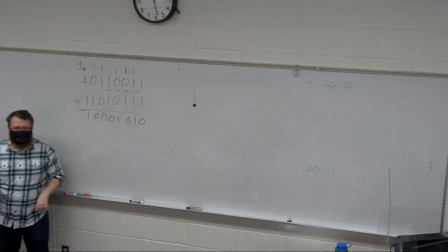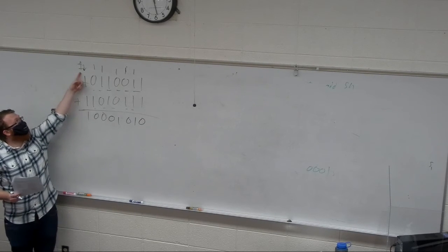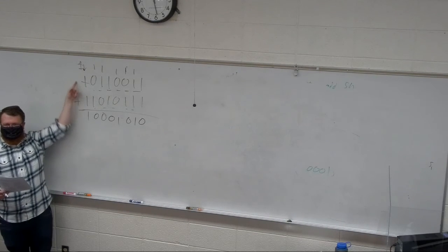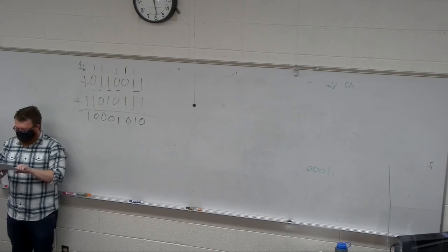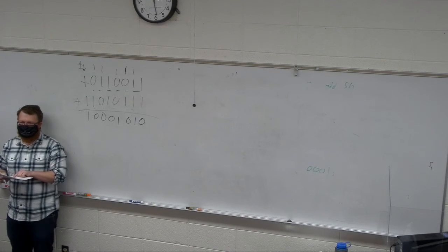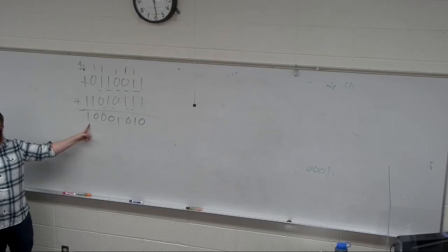Nope, you have to borrow. So that's your issue: if you have a 1 there, it adds up, and these two subtract. B, everyone got. The second one, or C, then had overflow, which was, so the mistake was there, is that these were two positive numbers that ended up with a 1 in the most significant bit.